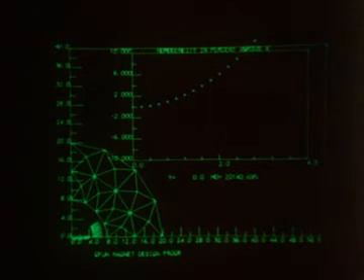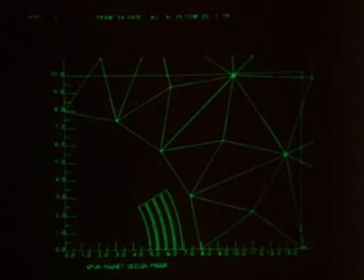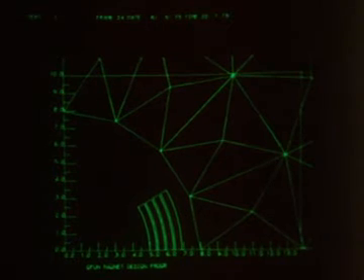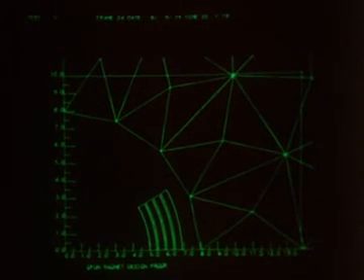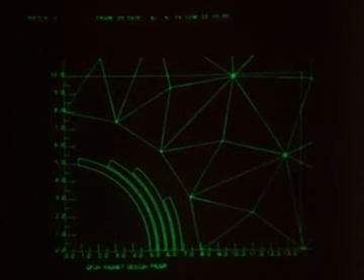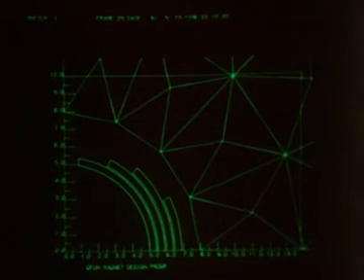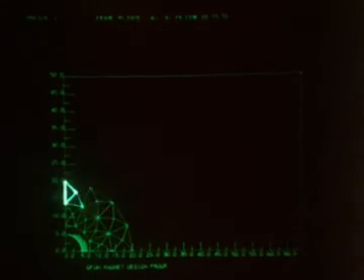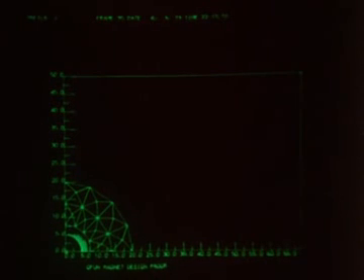In this case, the designer chooses to vary the angular arc lengths of the conductors. He initiates the automatic optimization routines which will vary the angles to minimize the field variation over the aperture. As can be seen, the new angles are now very different from the starting values of 30 degrees each. He rechecks the field, which is now within the required tolerance of 0.02%.